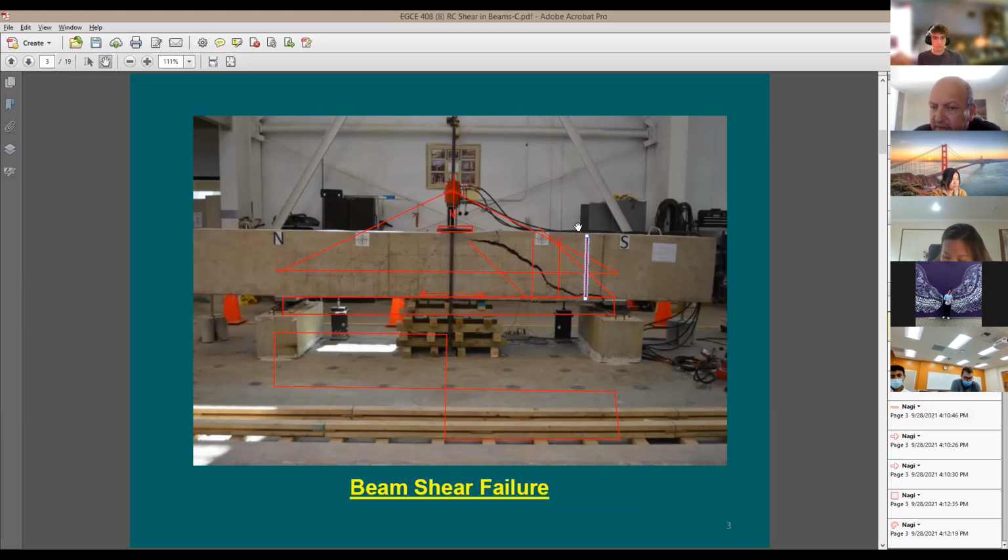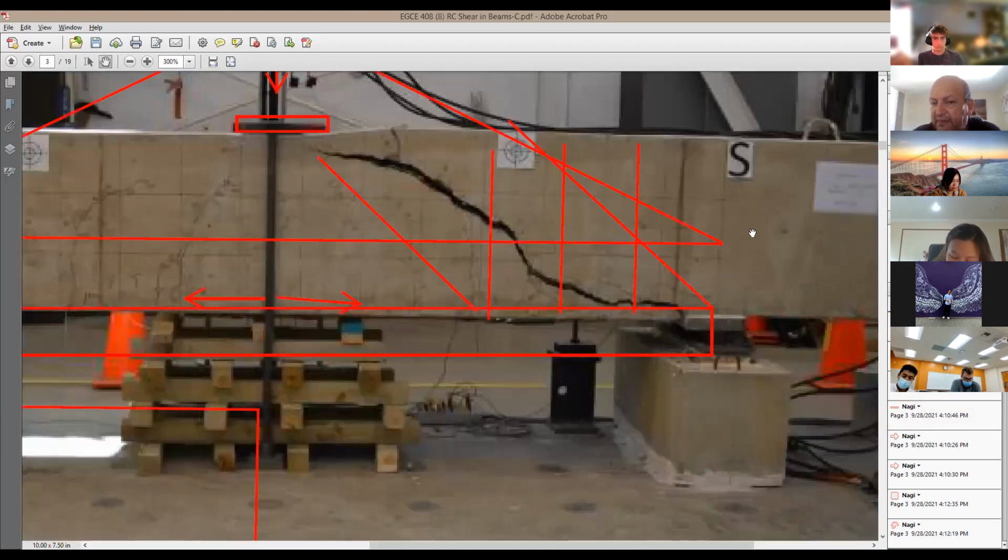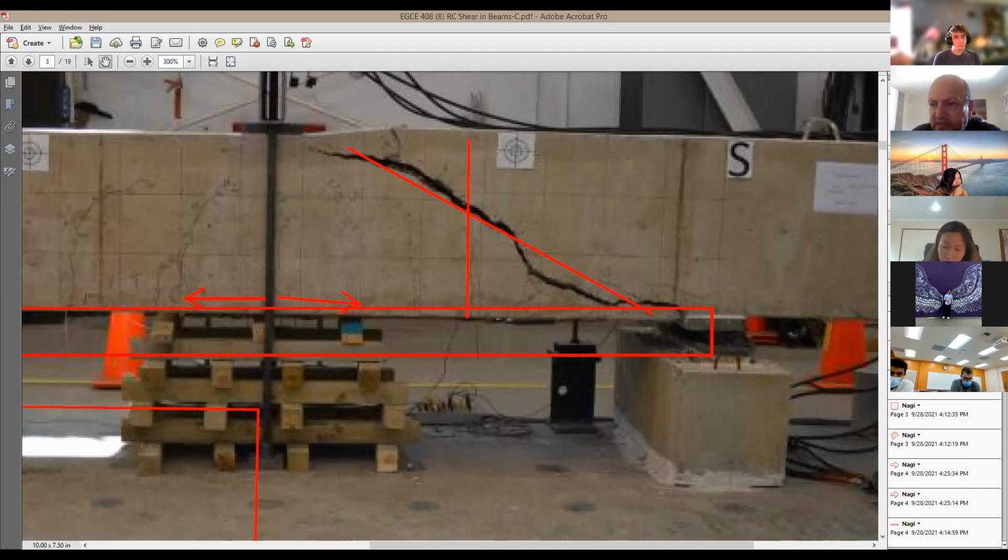And the tie spacing should be no more than 1/2 of the depth. Because if the crack is happening here at an angle, 45 degrees, let me remove this diagram and think about it in a good way. Here's a crack, right? It goes at 45 degrees. There are no ties, so the whole thing is going to collapse. So let me remove all of these ties. I'm going to put here 2 ties. Here's one of them, and here's the second.